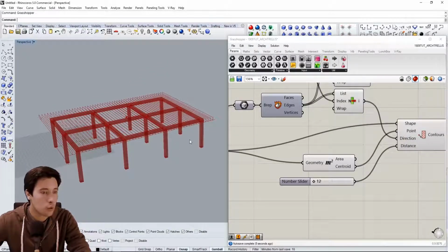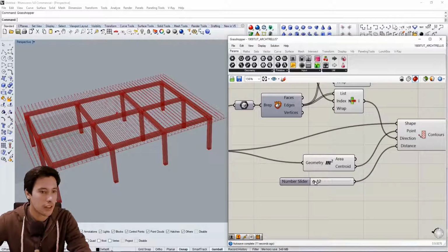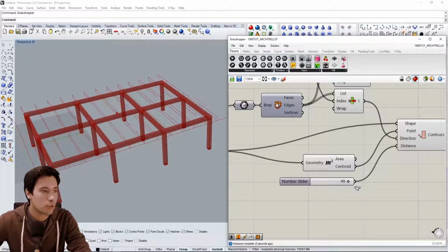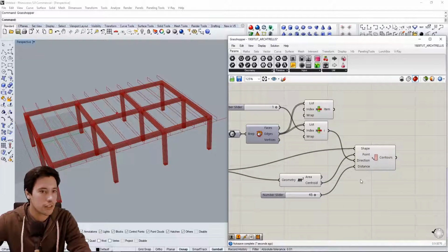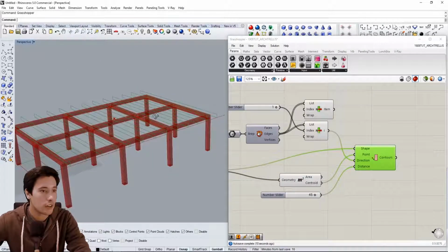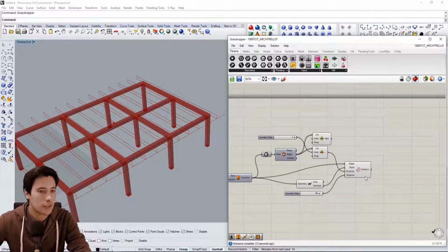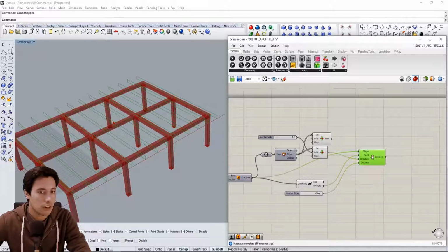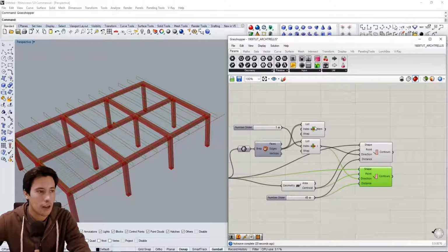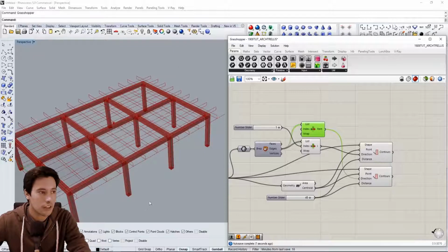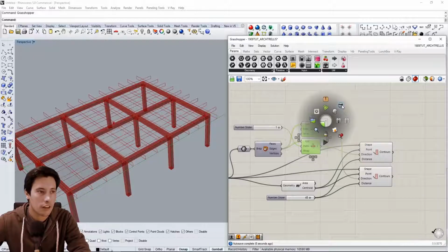And they're spaced out at 12 inches in between. So we can increase that to make it a little bit more spacious design, depending on what parameters we want in the end. But since we have it in just one direction now, we actually want to go in the other direction too. So I'm going to slide down, hit Alt, and then it'll make a copy. And then I'll plug this curve right into the other direction. So it'll create contours in the opposite direction also. And now we can select those two, hit the space bar, and then hide preview.